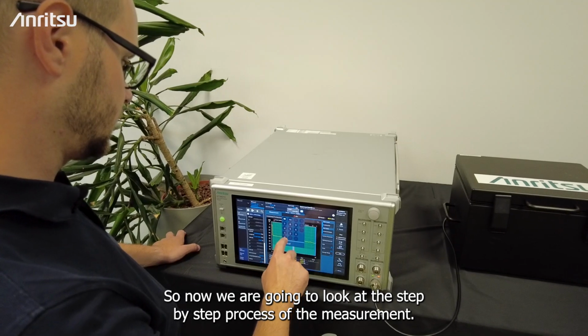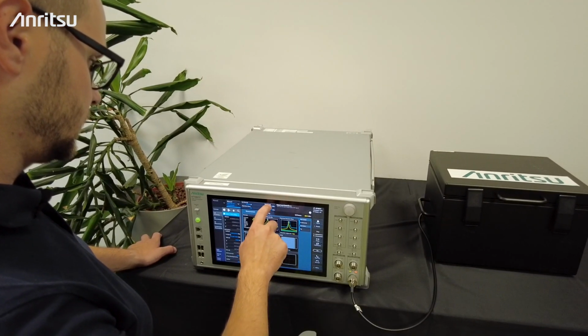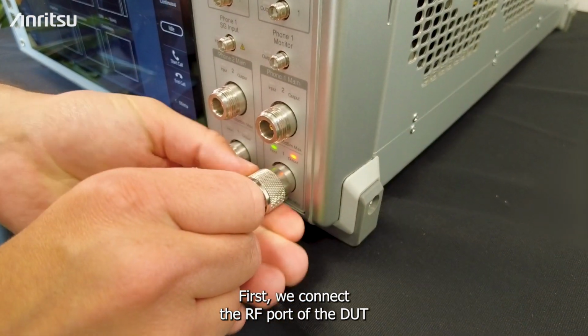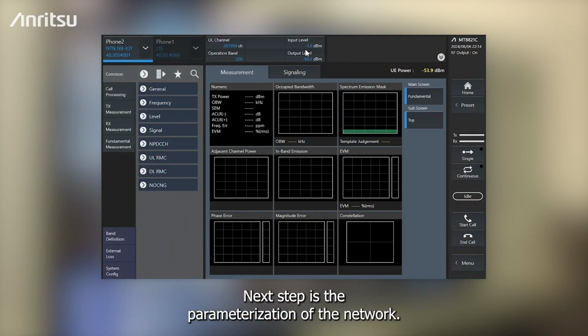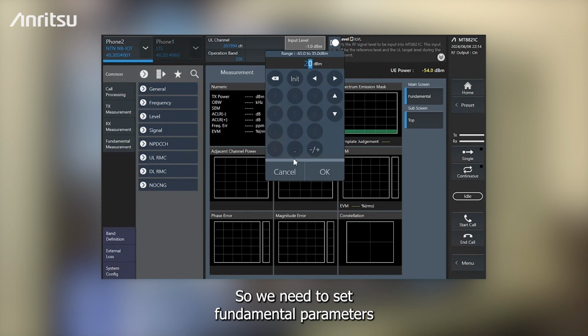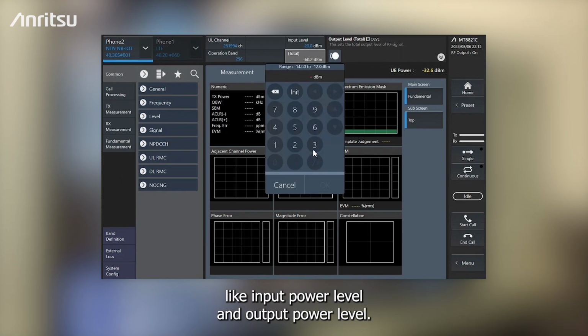So now we are going to look at the step-by-step process of the measurement. First, we connect the RF port of the DUT to our instrument MT8821C. Next step is the parameterization of the network. So we need to set fundamental parameters like input power level and output power level.